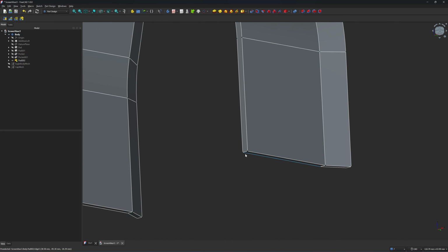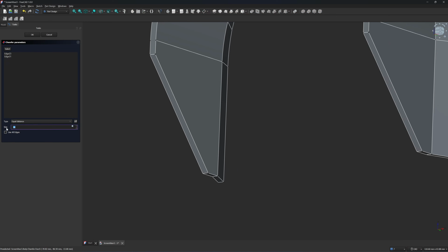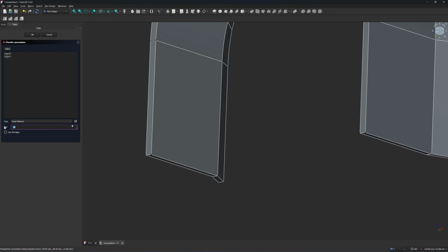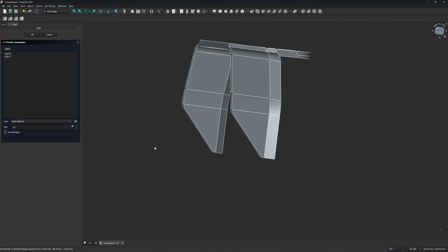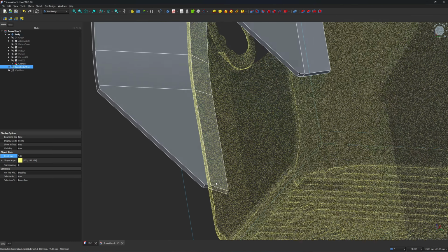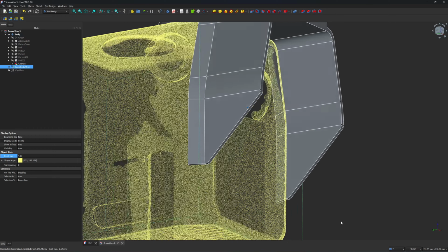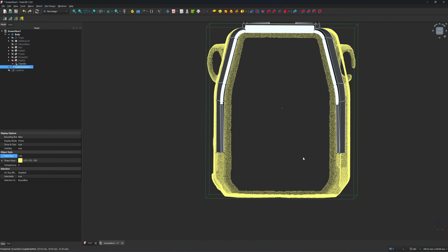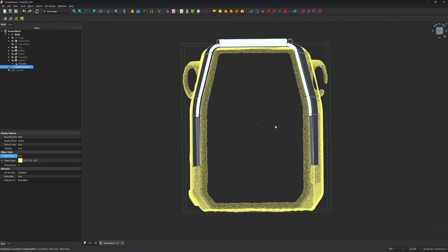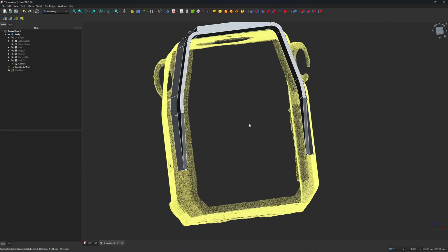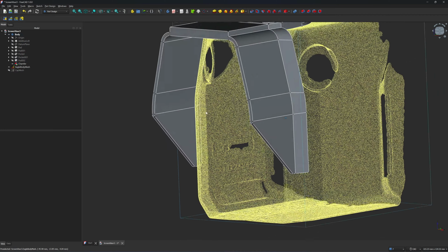Next I'm going to chamfer this edge and this edge. 30, 35, 35 cannot do, 30, 33. Okay, 33 is fine. The point cloud is touching the surface of the solid. See here, but when I print it with the ABS, it will deform after it's cooling. You probably need to print with the PETG or a PLA for a better result.